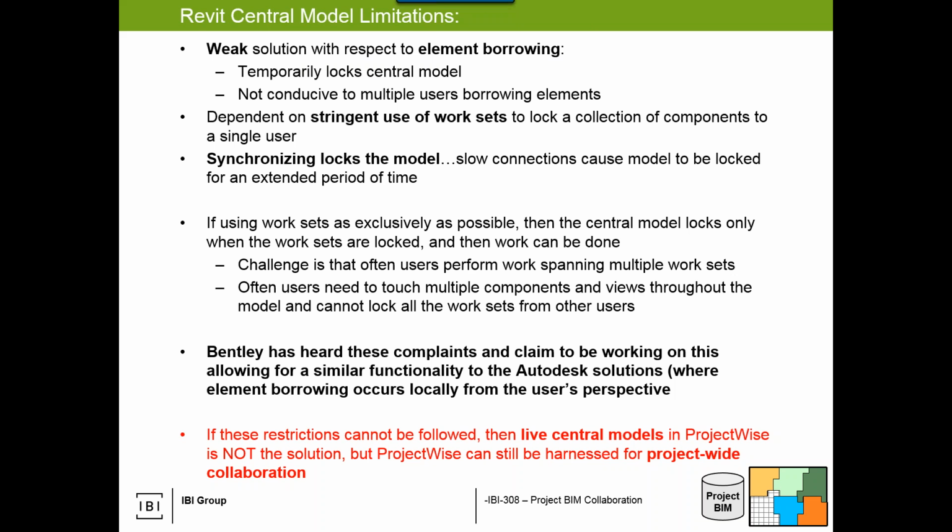So the way Revit works, when you have a central model, it has 6 backbone data files, or DAT files. Those DAT files log, if you will, the actions taken on the Revit Central model by a specific user relative to work sets, elements, views, etc. In quote normal solutions, so on your server, it uses an interlacing technology that takes what's on your DAT files and my DAT files, fuses them together when syncing to the central model, and allows for multiple communication to the central. ProjectWise's solution, unfortunately, only allowed for singular communication.